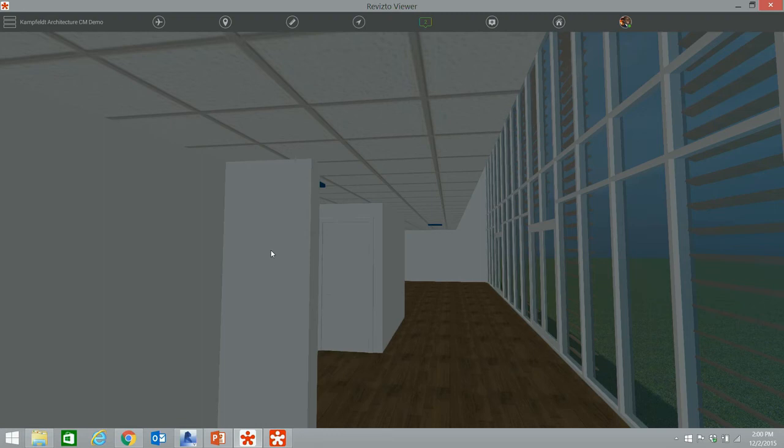This is something else. You can select which objects you want, let's say you can select only the architecture part, or MEP, or structural, and send only the structural to Revizto. Absolutely. Whatever is visible in the 3D view will be visible in Revizto, including of course the linked files, because linked files are also visible in the 3D view.